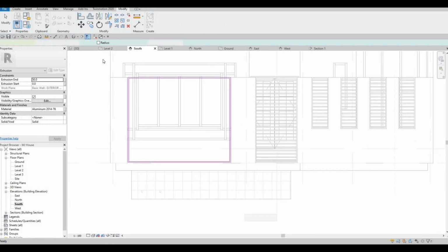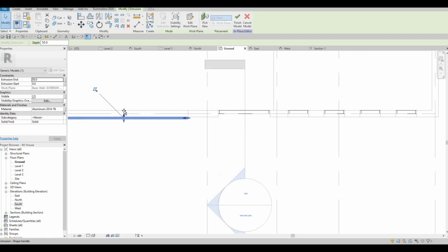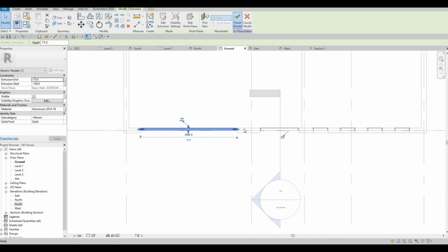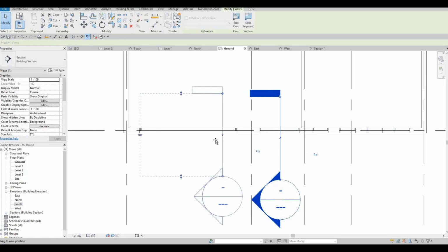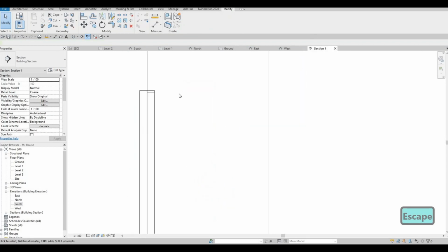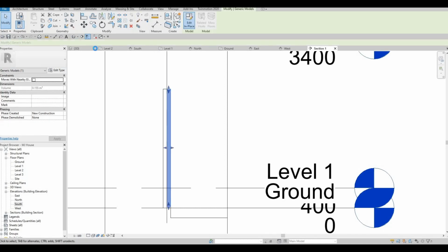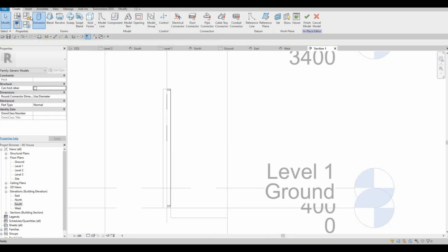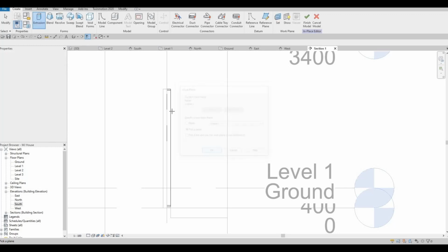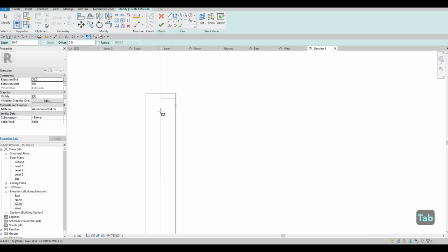And then after that, click on finish, go to 3D or go to ground in order for us to see where it is extruded, and then click on finish. We're clicking on finish so that we can move our section right here. So now we could double click here. This is the section 1. We could now select this gate again, add it in place so that it is similar, create extrusion, pick a plane, choose this one,